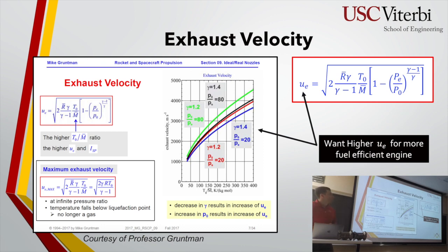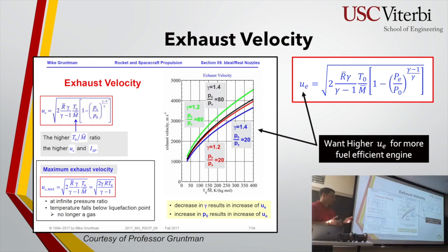Yeah. So wherever you see a naught, that means it's your stagnation temperature. Stagnation temperature means it's a made up thing. Stagnation variables don't exist. What it's saying is, if you have a fluid, it's comprised of potential and kinetic energy, right? Anything has kinetic and potential energy. It's saying, take this fluid and completely bring it to rest, so that it's not moving, and therefore everything is converted into potential energy, and that's what that value is.